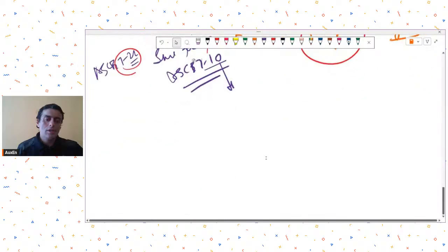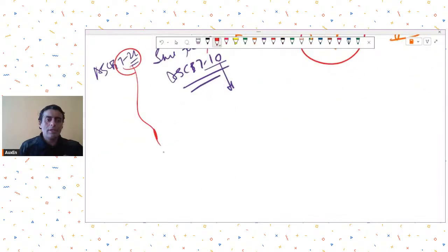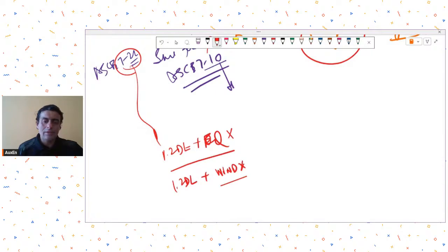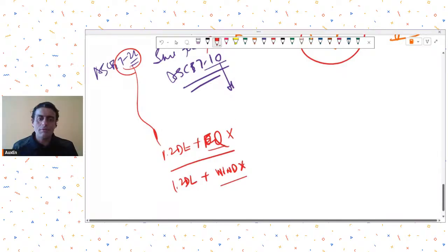Because of this, they have adjusted the load combinations by reducing the factors for wind and EQ. Do you understand? So now the wind and EQ are, let's say, with a factor of 1. Why? Because the magnitude has been increased. So to keep the overall load combination value similar, now they have reduced the combination factors.